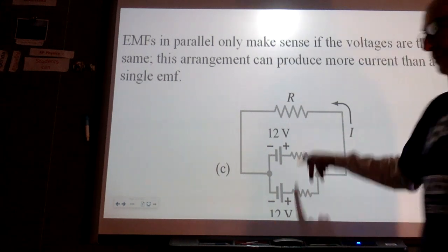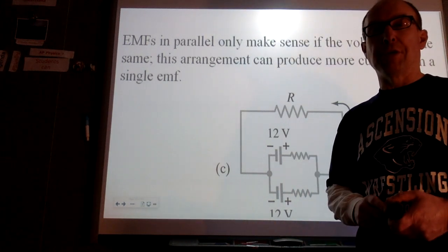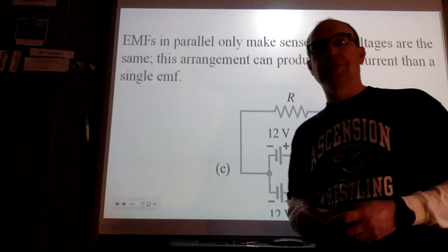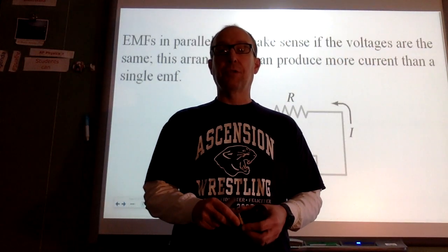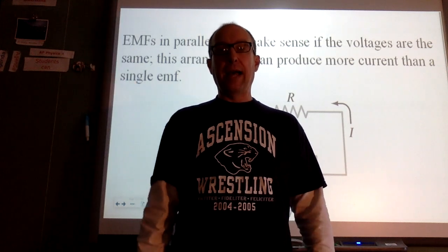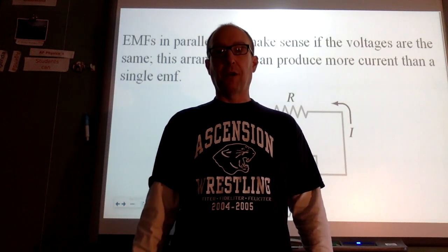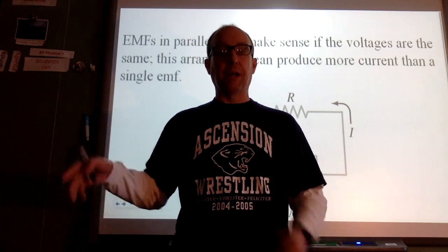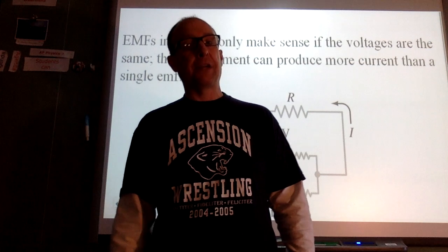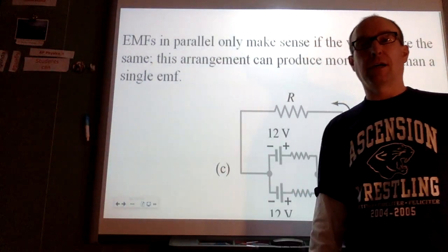In parallel, you don't increase the voltage, but you get more current. When I was your age, I worked at a marina, and we had forklifts that lifted boats and stacked them 4 high. And the batteries that started a forklift are very much like car batteries. They needed to be 12 volts, but we had 2 of them. So you have 2 in parallel, so you can get more current to actually start the forklift up.